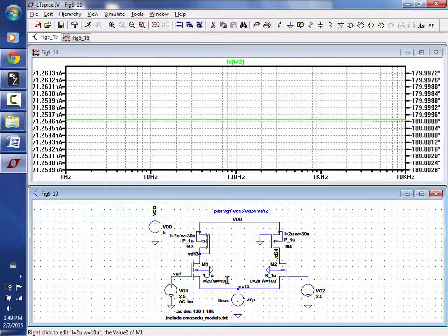Is anybody confused by that? If I say this, because of body effect here, we have slightly lower. So for example, we calculated this as 2.45 DC-wise, or 1.45, and it's 1.17. Why is it lower than what we calculated by hand? Don't say body effect. Yes, it's body effect. Well, the threshold voltage goes up. When the source and the bulk aren't tied to the same potential, you steal charge from the channel and it raises your threshold voltage. If the threshold voltage isn't 0.8, it's 1, then obviously this node voltage for 20 microamps flowing through it is going to go down.